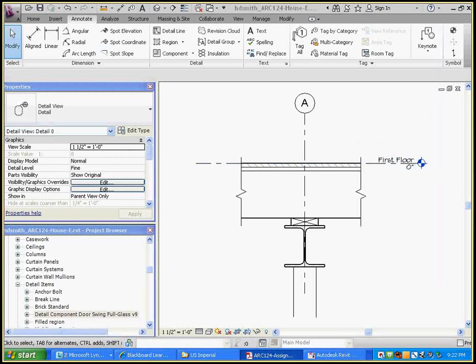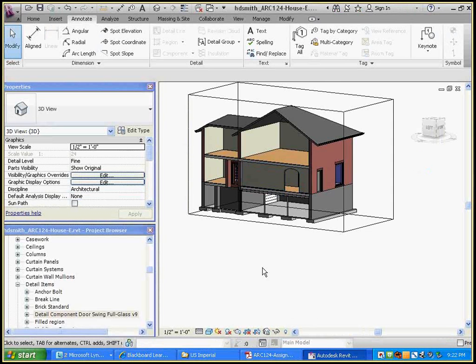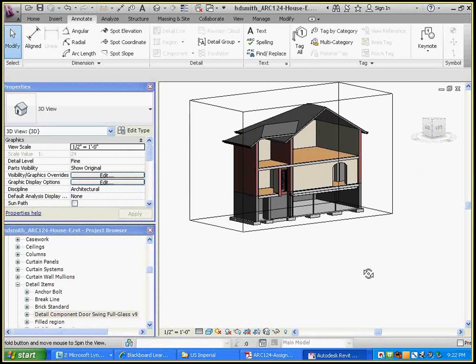Good point. And that's the other downside of dropping the beam down, is that that door hits the beam and you've got a conflict. And part of the reason I kind of left this in here is because it shows how when you build things in Revit, you're doing more than just drawing a framing plan or a floor plan and an elevation. You're actually resolving things in 3 dimensions. So our building may be a really simple little rectilinear building, but we're looking at it in 3D and we catch things that we wouldn't otherwise catch if we were just drafting it in AutoCAD.